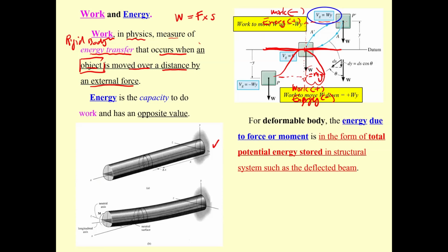However, if you have a moment bend it, then by bending this one, the beam is going to have a curvature. If this is the radius of the curvature, the inverse of the radius of the curvature is going to be d squared v by dx squared equal to M over EI.